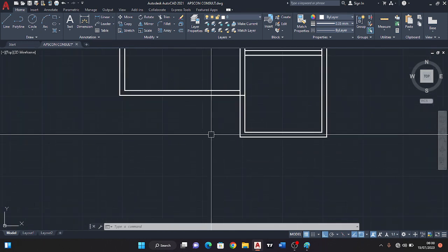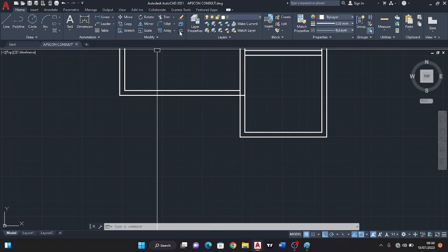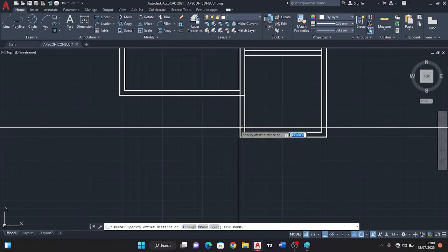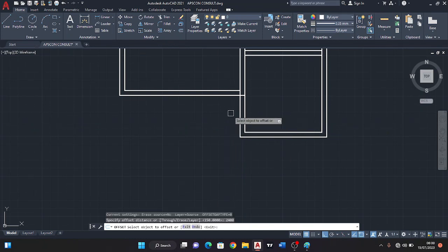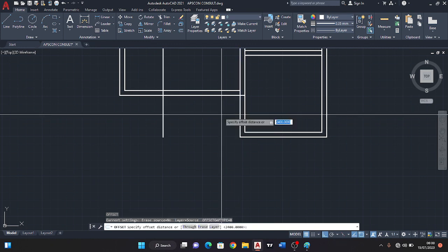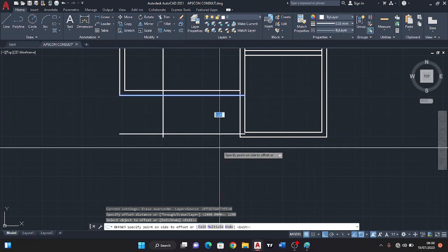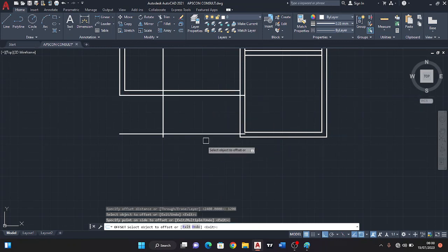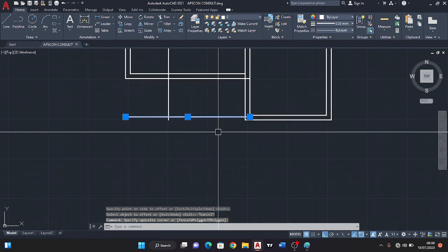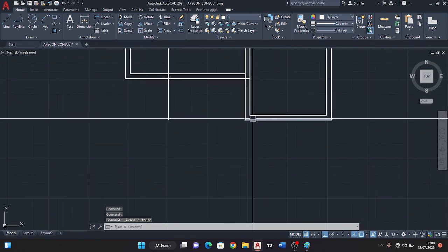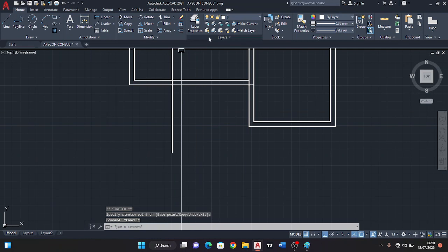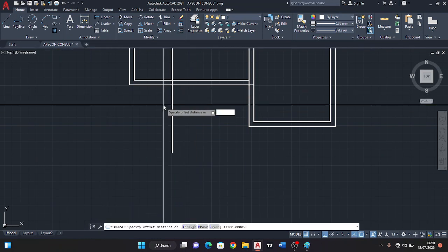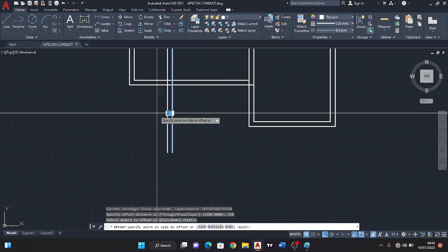Now I'm left with creating my veranda. Let's assume my veranda should be 2400 by 1800. Let's say 2400, enter, by 1800, enter. Okay. Now for the fact that I want the veranda to align with this wall, I can just click and drag this up. Now offset that place to have my 150 thickness block there, which is this.